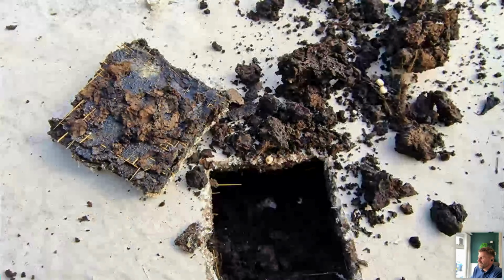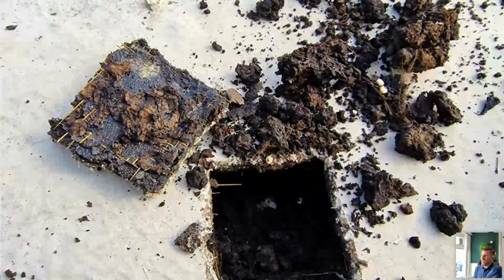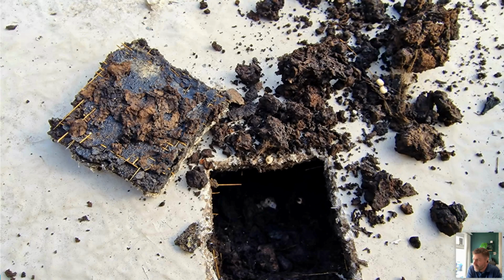This is one that we don't see much of these days. Cork insulation isn't produced anymore. The manufacture of cork ceased in around the late 90s, just because of the cost of it. One of the reasons that cork was introduced is that you could fully bond a bitumen system to cork, because the cork is inert, therefore it doesn't gas, so it doesn't blister.